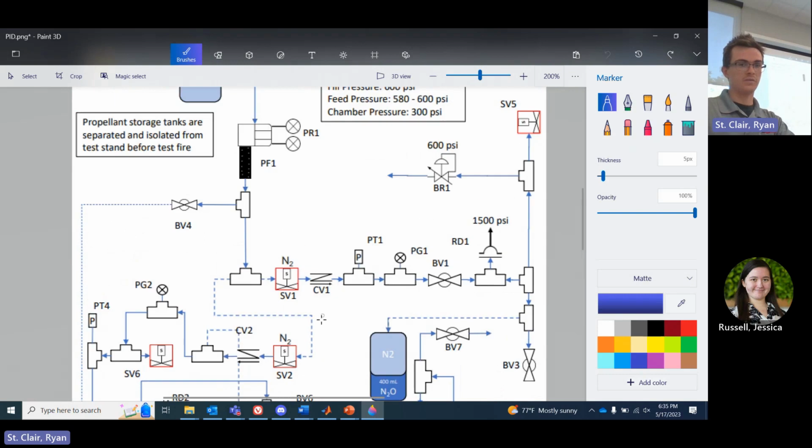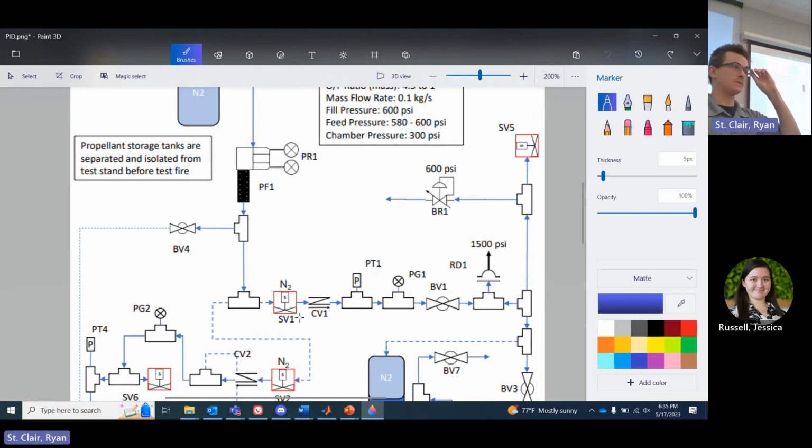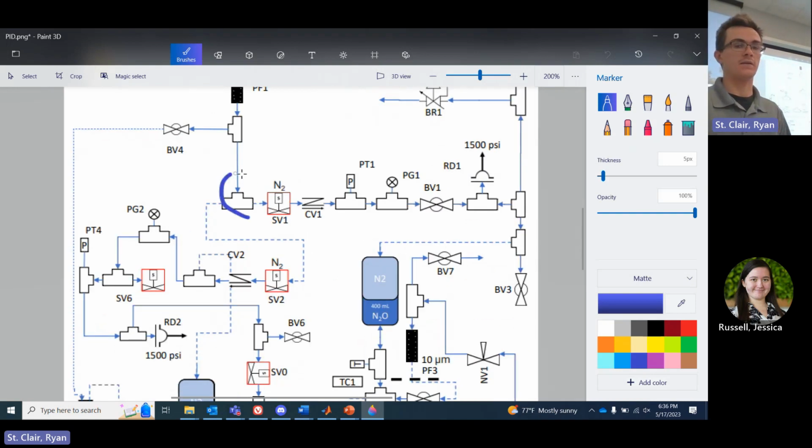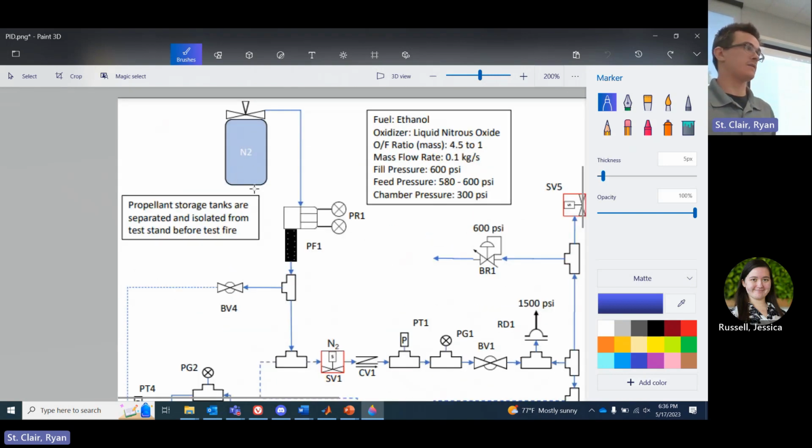That was a design choice that we made to make it a little more realistic for what you might see on an actual rocket or a lander, because there's very little room in a rocket to have two tanks of pressurant, even though it technically would be less of a headache. Because then your fuel and oxidizer systems are completely isolated except at the injector. It is kind of a pain having them connected here at this T right here, but we do this to make a scalable design.